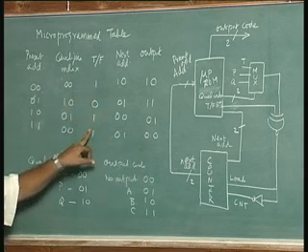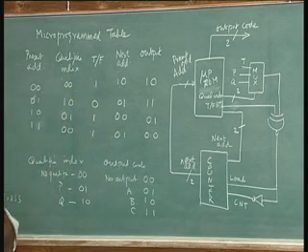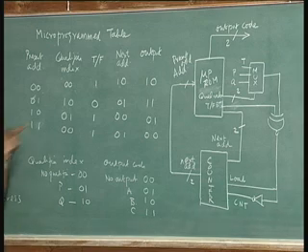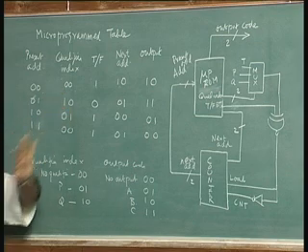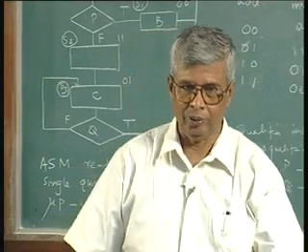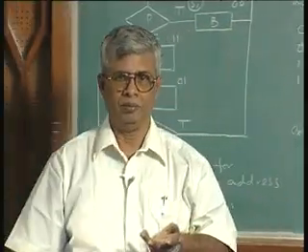Instead we have an extra column of true false bit, and the qualifier index. Unfortunately there are only 2 qualifiers, 0 and 1. Single qualifier double address case, we need a qualifier address 0 or 1. Now, I have increased 1 bit for the qualifier index and 1 bit for this, so I have not had any saving. But imagine the number of states are very large.